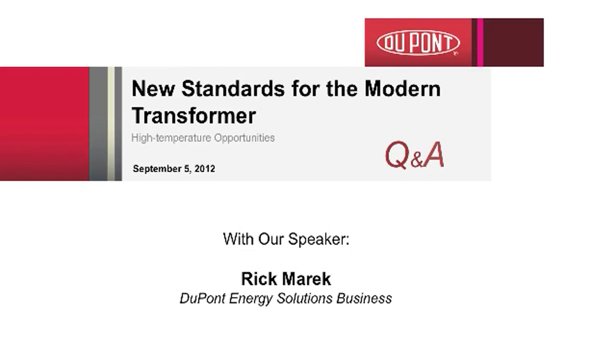And along those same lines, a question just came in asking, what will be the temperature class of kraft paper and Nomex for high temperature liquid immersed transformers? Well, you would want to look at them individually. Of course, the thermally upgraded kraft paper is a 120 class, and